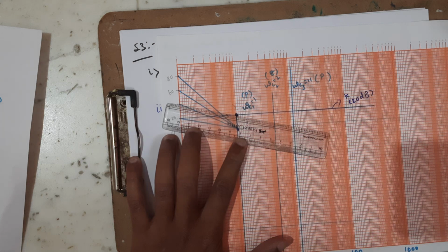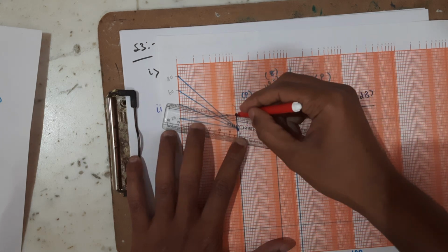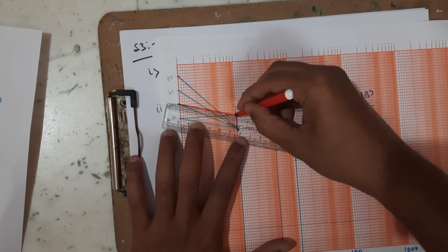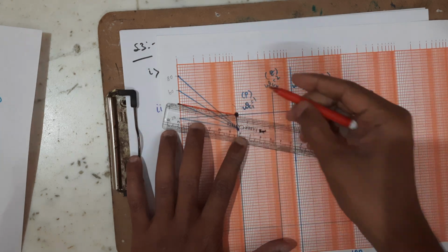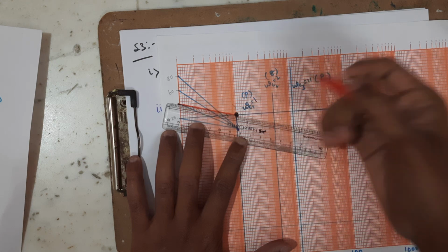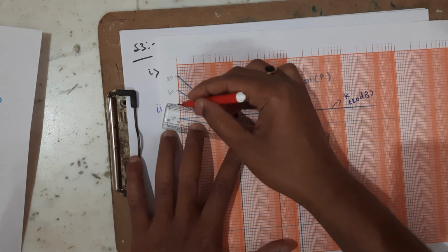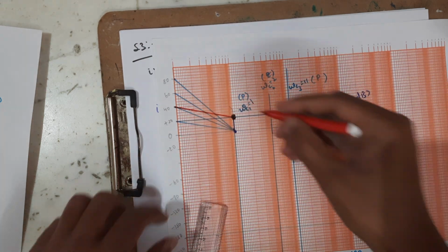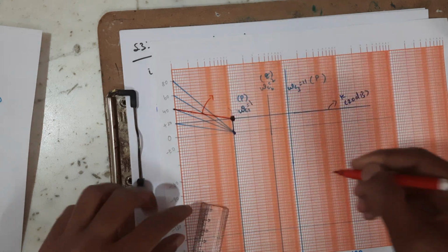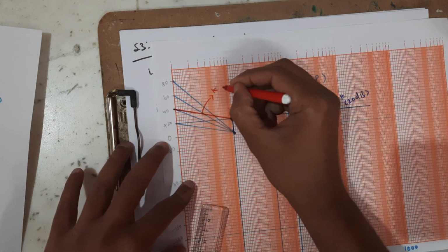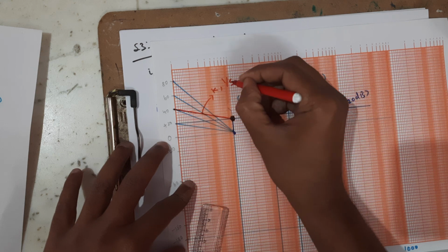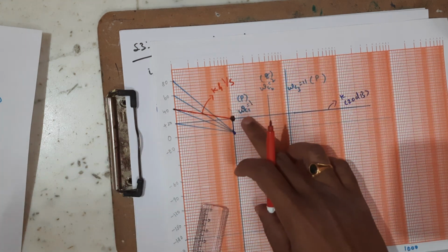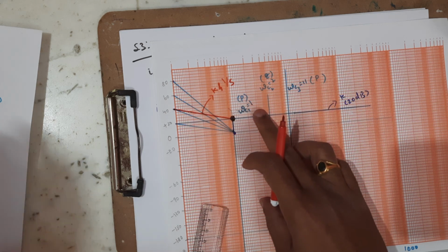I am going to draw the slope of minus 40 from this point, and I need to extend it up to the corner frequency 1 and make a note here. Here omega C1 is equal to 1 radians per second. So this will be the line up to the corner frequency 1. This line is due to the contribution of K and one pole at the origin, that is 1 by S.